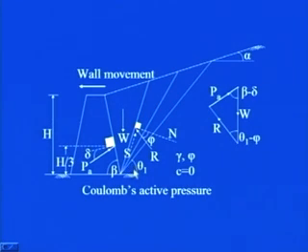As you can see here, I am showing this angle by theta. So, if I consider this trial wedge, what will be the value of theta? Theta will be the angle which this face subtends from the horizontal. So, we know the magnitude of W, we know the beta minus delta angle, we know the theta 1 minus phi angle.